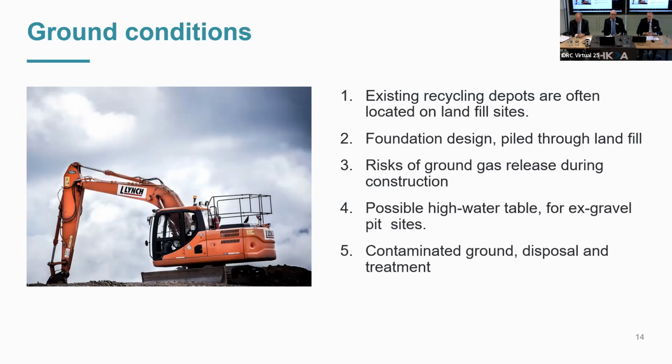Also, there may be considerations as you're piling or digging into landfill sites, this can release methane gas, and this can be both hazardous and a huge impact on the environment. If you are working on a site such as previously gravel pits, which are very common around the London area, they can have very high water level tables.